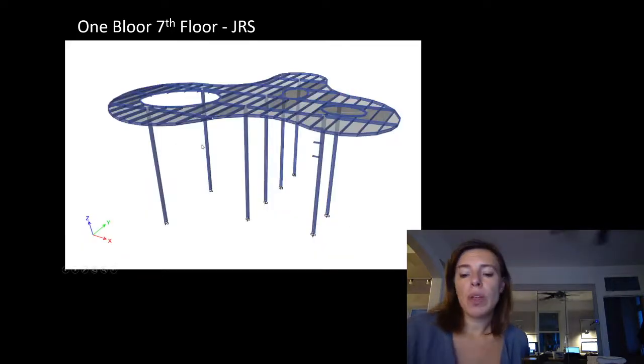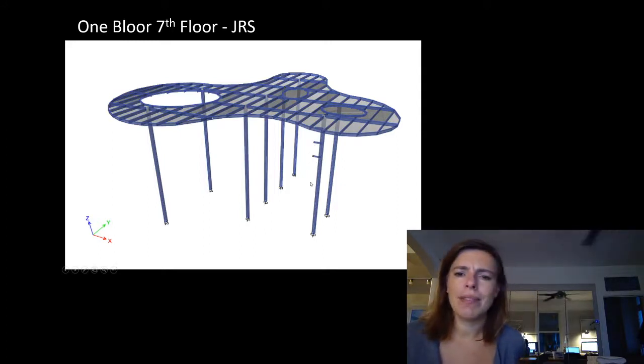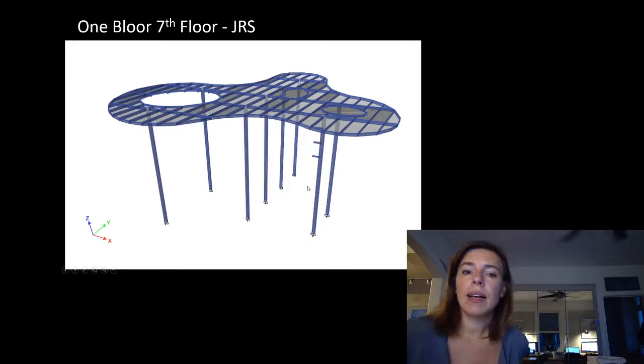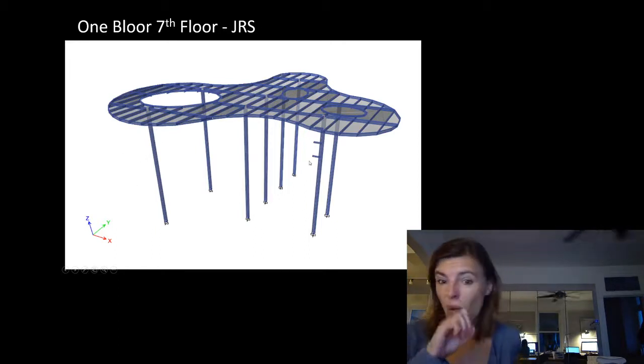Here's what we ended up with. These were kind of the original drawings. We did lots of iterations where they changed to one big opening here. And then after this was already designed and fabrication had begun, they decided they wanted to infill these openings. So I had to go back and check if we met all of the criteria for that. These two little stubs were for, I believe, lighting of some sort. And they were heavy lights, so we wanted to check for bending on this column. It was probably applied to all of them, but I just needed to check one to see how it worked.